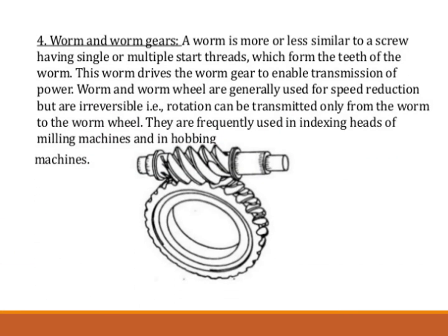Worm and worm gear. Another form of gear used to connect shafts whose center lines do not meet is the worm gear, which differs from all the preceding types of gear in that one element is a screw and the other is the worm gear with involute teeth. Worm and worm gears are used when a large speed reduction ratio is wanted from one shaft to another.